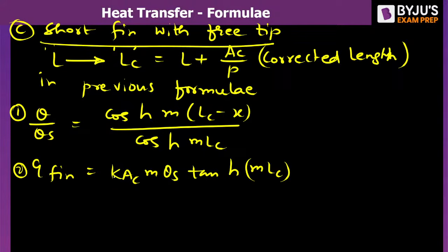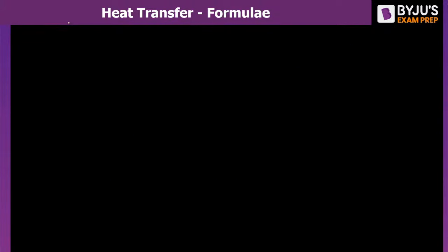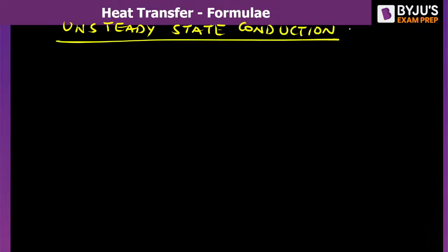These are the formulas for short fin: in all the previous formulas, we can replace L by Lc. So that completes our fin theory. The next is unsteady state conduction, when temperature is a function of time.